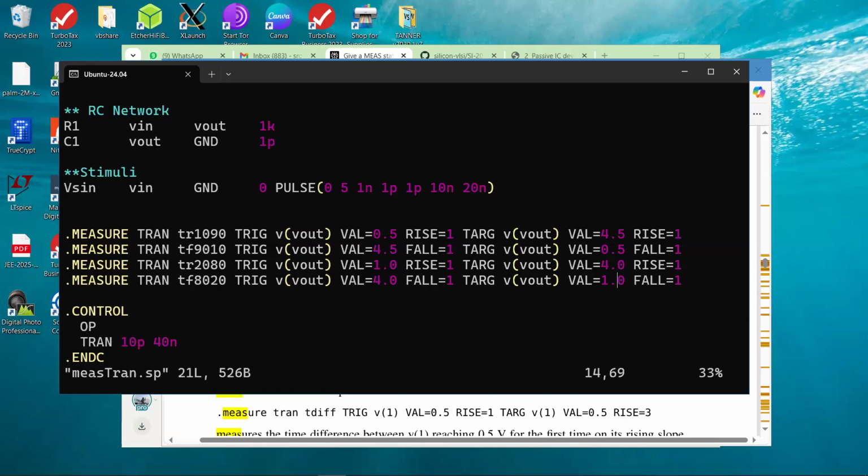And then the pulse width is 50% of the output rising to 50% of the falling. That's pulse width. And the period is from rising 50% of 1 to rising 50% of rise 2. This is where you're going to use the rise 1, rise 2. You got it?